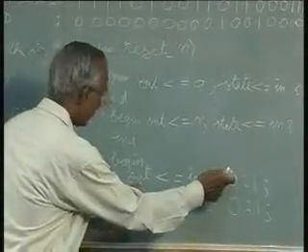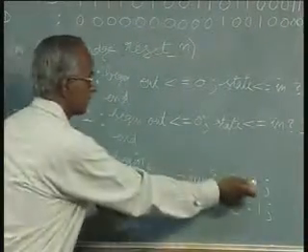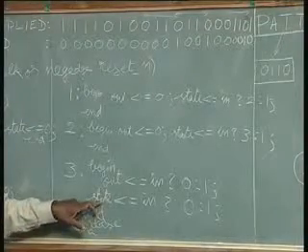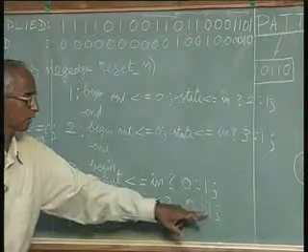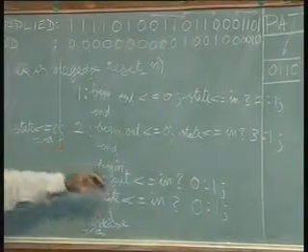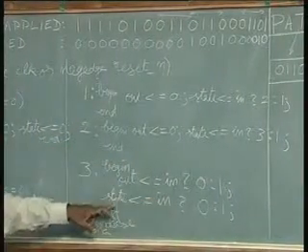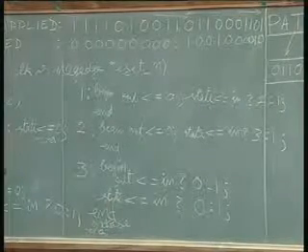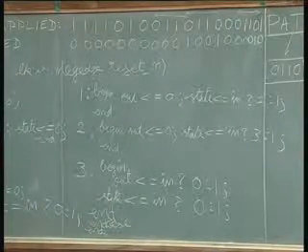So either 0 is assigned to output or 1 is assigned to output. So is the case here. State is assigned either 0 or 1. In the case where it is 3, let us say, you naturally need 2 bits here. So state is 2 bits in width, whereas out is just a single bit.